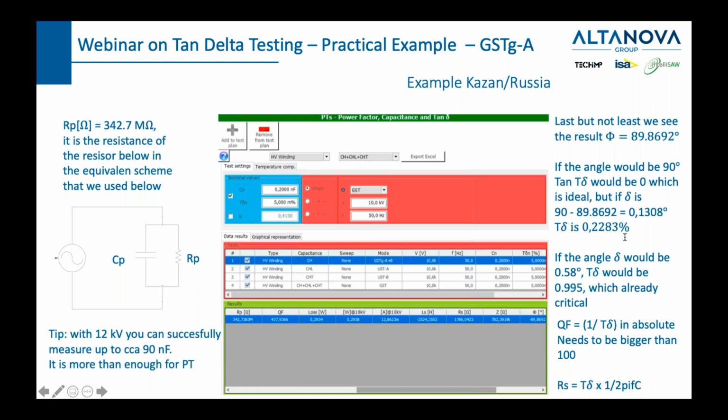You can go maybe 10 or 20% higher than the nominal voltage, because we don't generate voltage for a long period of time. It's maybe 5 to 10 seconds. But still, especially if it's an older asset, don't go higher than the nominal voltage. So 400 volts should be the correct answer.